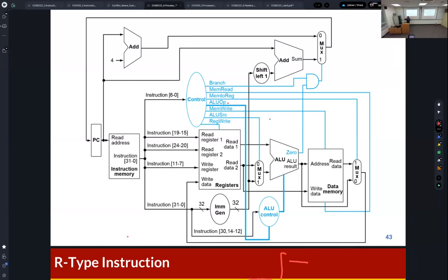We defined the required steps: instruction fetch, decoding or register read, ALU execution, memory access, and register write, based on the instruction. Then we defined each data path element, and the data path elements are connected to each other. So the data path is complete.